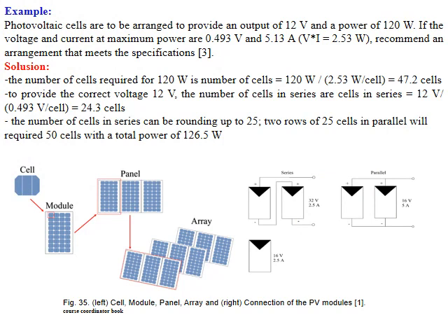Now solar cells, as I mentioned, we connect them. You have the cell. You connect them in series and parallel in this way and this way to come up with a module. Putting modules together, you come up with a panel. Putting panels together, 1, 2, 3 for example, you come up with an array or power plant. And this is the series connection, as you can see here, current from here in this way, or the parallel connection.